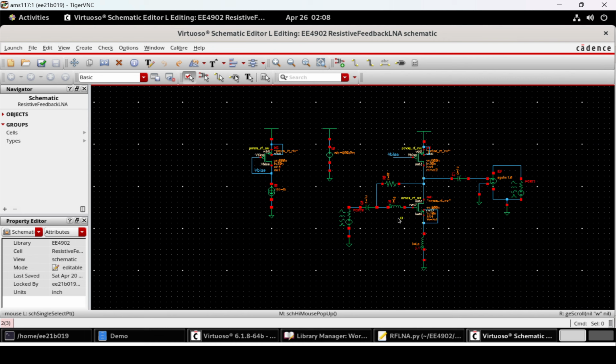I have added certain biasing details such as these inductors to input match the given network 250 ohm, and the initial DC operating point is picked such that the input impedance looking in from the input port is 50 ohm. That is the starting point, and these AC coupling capacitors are added to not change the small signal picture.